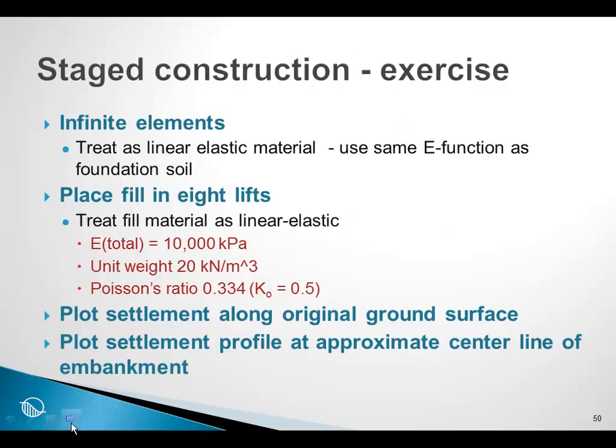The infinite elements will be treated as linear elastic and use the same Young's modulus function as for the foundation soil. We're going to place the fill in 8 different lifts using a linear elastic material. The stiffness is 10,000 kPa, unit weight 20 kilonewtons per meter cubed, and a Poisson's ratio of a half.